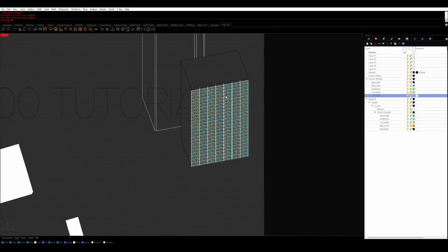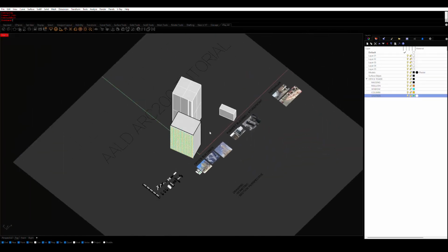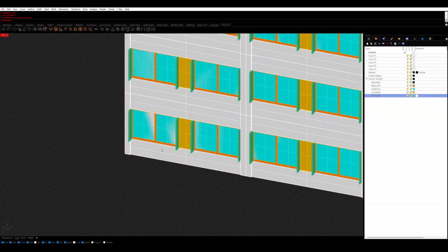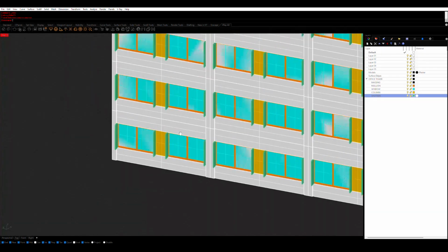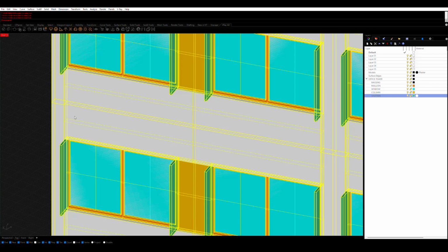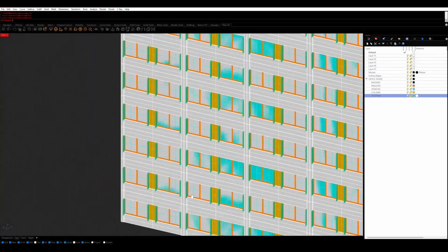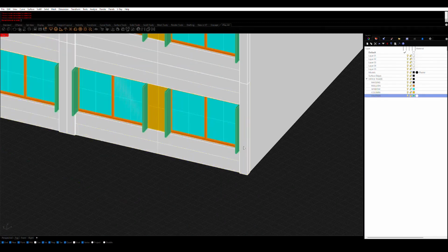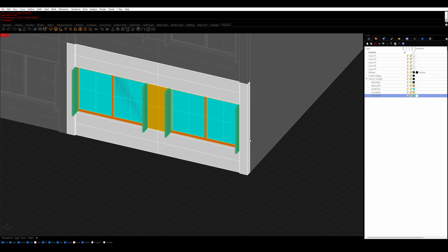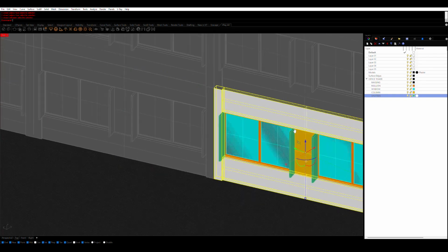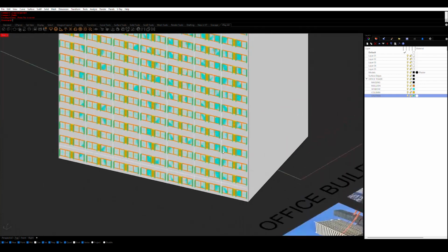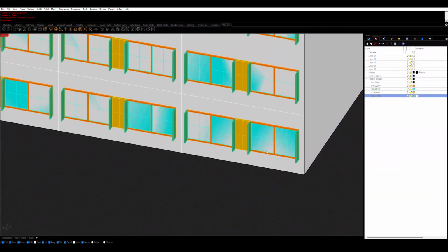And what that's going to mean is that we're actually going to have to make some edits to our block. So what we'll actually want is to have a separate geometry that kind of covers both these portions, and then also columns that kind of span the entire height of the tower. So what I'll do is I'll go into the block. I'll actually delete these objects, but maybe before deleting them, I'll just copy them and then delete. We'll hit OK. And of course, all of them will disappear.